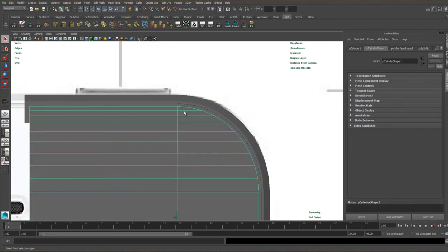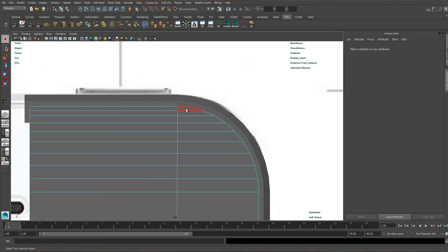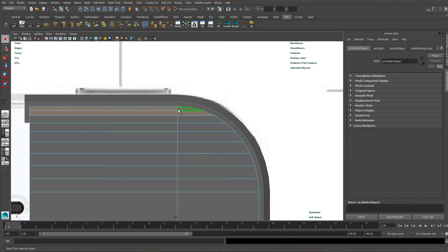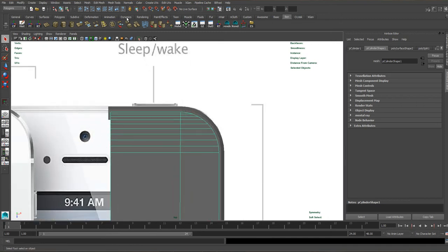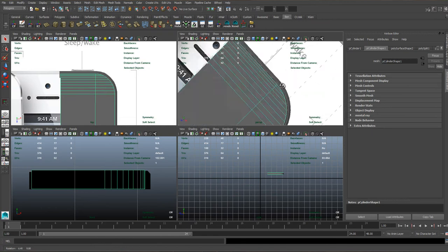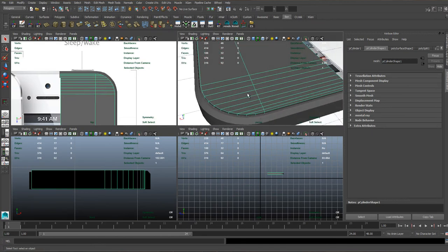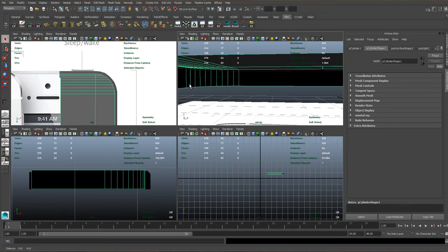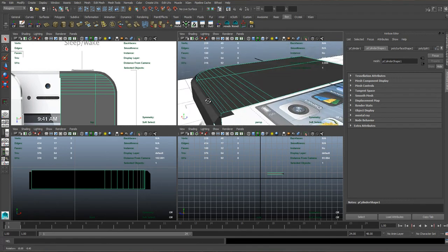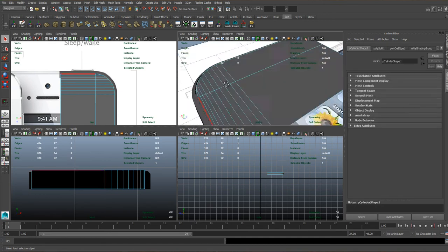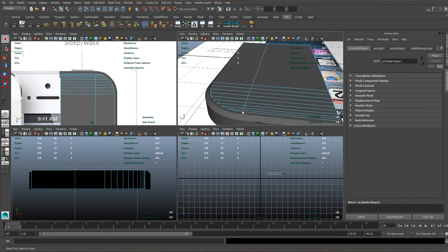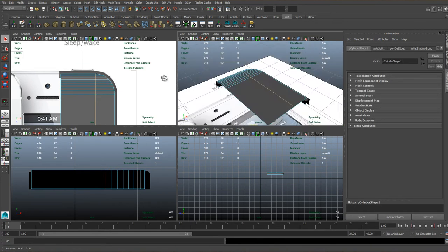Instead I've added an edge going down there. I suppose you could keep on repeating that process if you want. If these edges were still too small, you could get rid of these edges here and make them vertical instead. And when you're using the multi-cut tool, it's really important that you check to make sure that you have created an entire edge loop. I know that my geometry's not yet self-contained, so I am fine because there was already an edge here, and I'm just extending that edge all the way down there, and then it hits the end there.